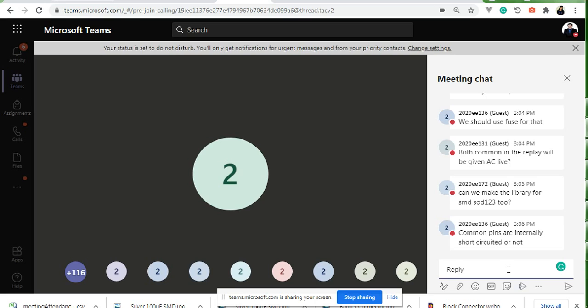I have told you previously also to make your text at least 1.7 mm to 2 mm in height with a thickness of 0.3 mm, because if you make it very thin, it won't be printed even over there. If they are using UV light for that PCB, or even some other method, and it is very thin, it won't actually be visible. So your PCB will not have those names, your name will not be there. So please do that. I have asked them personally to make that editing, so they are taking time for that editing also.